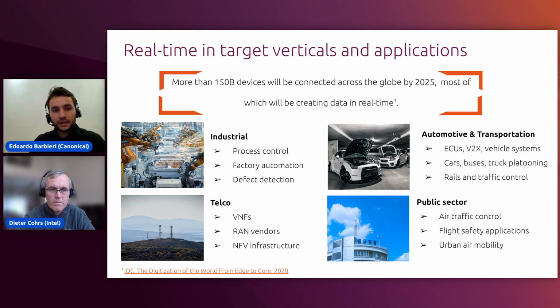You could imagine that to maintain the system integrity, to maintain the continued production, the PLCs in an assembly line must be able to process and to deliver data in real time, because a missed deadline could compromise the entire production line. Also, if we think about the effects of real time, about the consequences of a missed deadline being catastrophic, then all sorts of other use cases and workloads can come to mind.